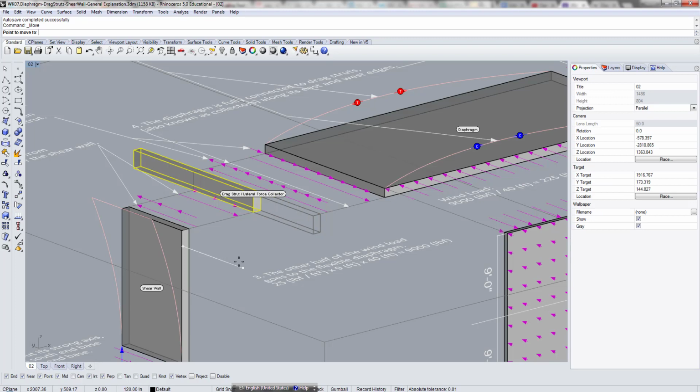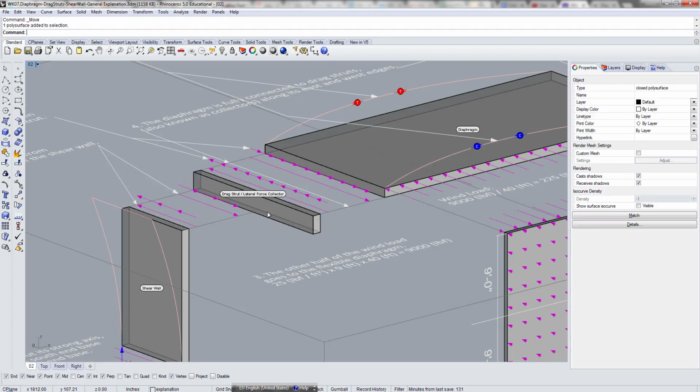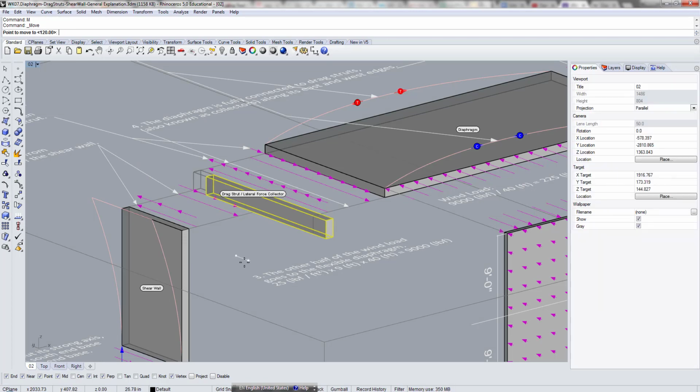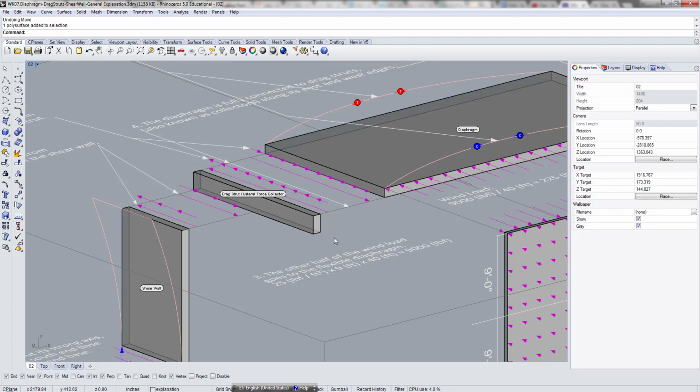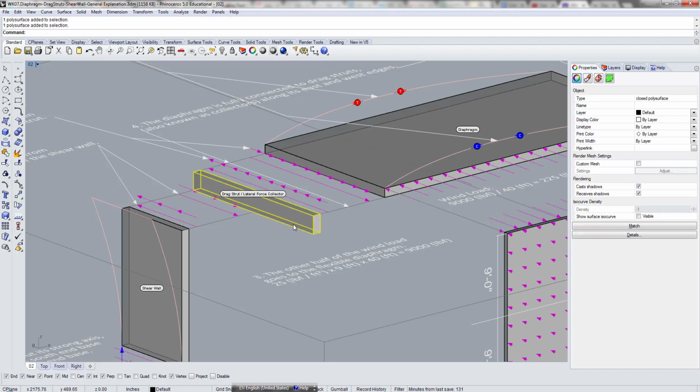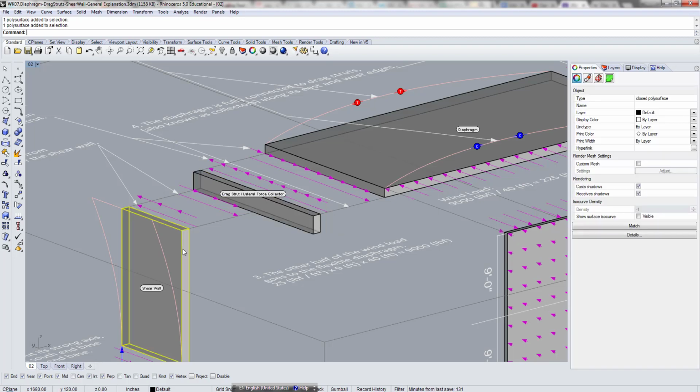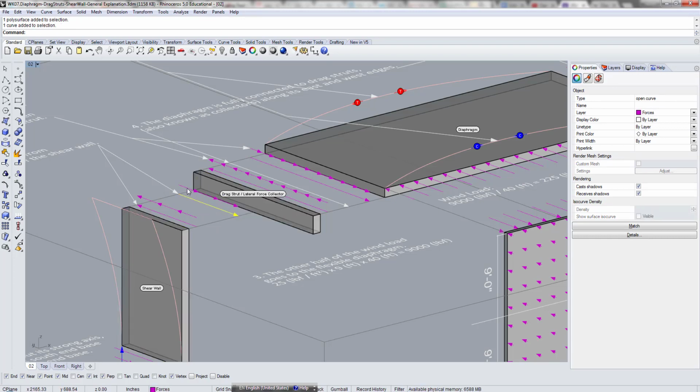But it's not moving because it's being pushed back the other way. It's not being pushed back on the upper side, because on the upper side the only thing happening is the diaphragm trying to push this collector that way. So the only way this can resist is through the connection to the shear wall. So the shear wall now is going to push the other way.